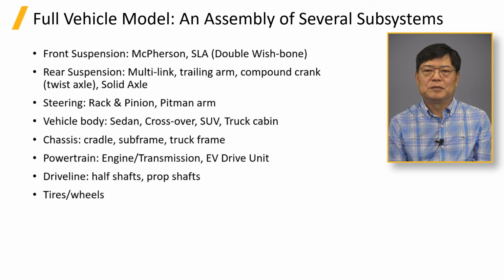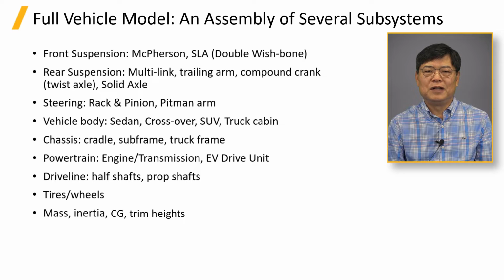A simple bicycle model cannot answer overall steer ratio, vehicle roll characteristic, suspension component load, and embodied structure sensitivity to NVH performance. A simple vehicle body model could be a rigid body of mass, CG, and moment of inertia. The body also can be high-fidelity FE models to represent the compliances as well as inertia properties. Passenger and luggage mass should also be comprehended in the full vehicle with a vehicle ballast.